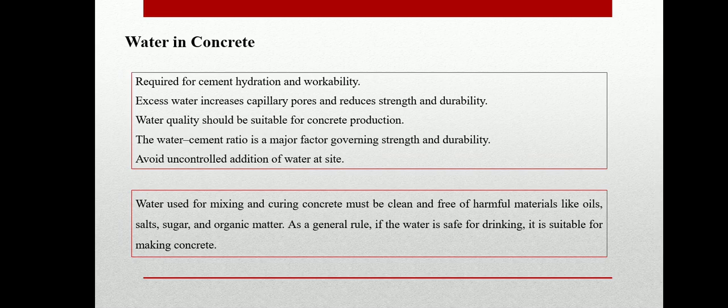Next, water. It seems like the simplest ingredient, but it is arguably one of the most critical ingredients in concrete. Water is required for two things: hydrating the cement and providing workability so the fresh concrete can be mixed, placed, and compacted. Though excess water is dangerous, here is the catch.